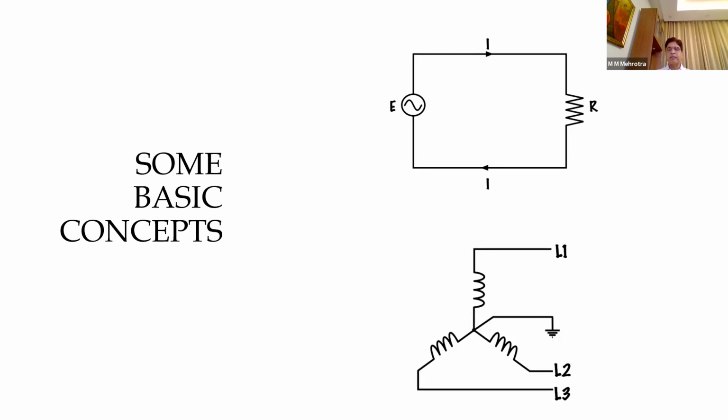So it will be some vector sum, 20-30% of the normal current. If the circuit is unbalanced, things will change, right? The current in the neutral conductor will increase when the three phase currents are unequal. When these are unequal, there will be some resultant current in the neutral.